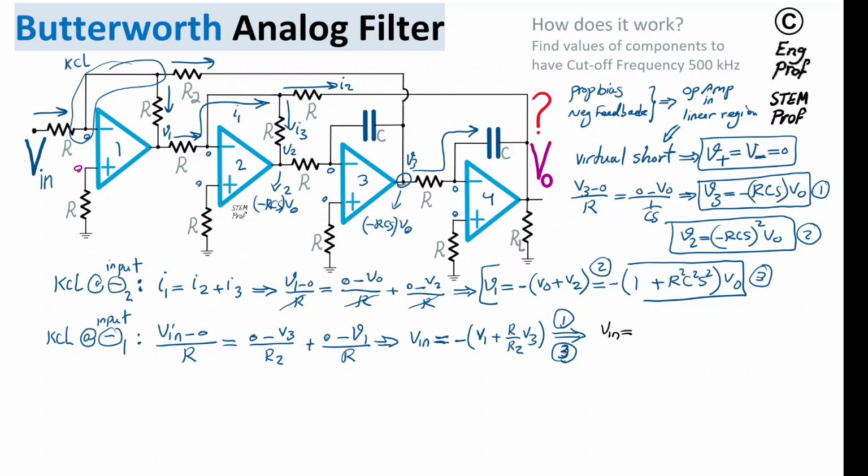And I get Vin is equal to minus, so there's another minus here, it will cancel out this minus here, but let's keep it so that I'll do it in another shot. So R squared, C squared, S squared, and then minus R over R2. I'm just substituting V3 here, which has a negative sign as well. So that's why I wrote minus, and then we have RCS and Vout. So we are almost done.